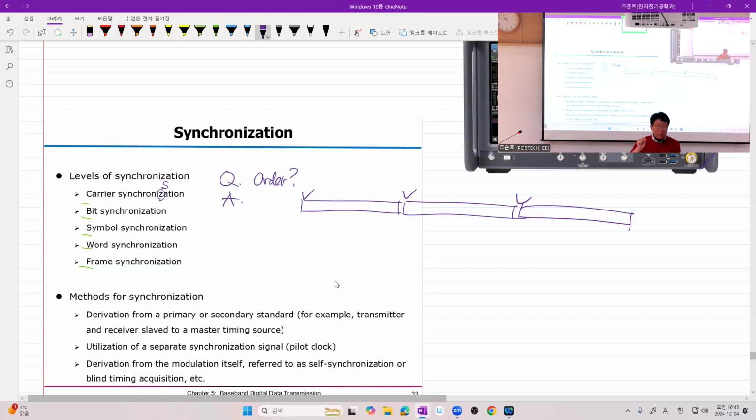And I read the lines of their code and found that, given the very low signal to noise ratio, the Raytheon engineers were trying to recover the carrier frequency first by using a squaring loop. And it didn't work, of course, because the signal is designed for a very weak SNR environment.